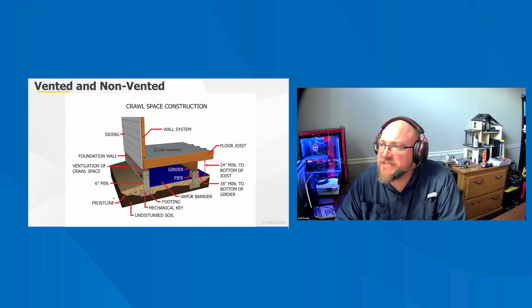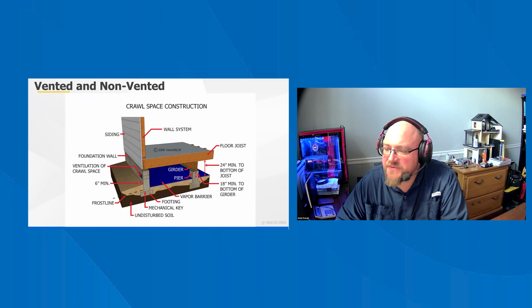There are essentially two choices for ventilation of crawl spaces. The first follows conventional ventilation practices, and the second follows a non-vented crawl space design strategy. When vented, the underfloor space between the bottom of the floor joist and the earth under any building except for a basement should have ventilation openings that allow air to pass through the exterior foundation walls.